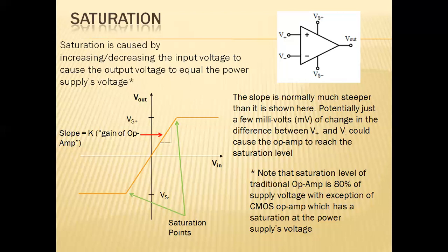Considering the gain of the operational amplifier, it is shown here with respect to the linear increment of the voltage input, the corresponding output is generated. This is linear. Up to where? Up to a maximum point, the saturation region. Even if further input is supplied, there will not be any gain in the positive portion. It will be constant, stabilizing at a particular point.